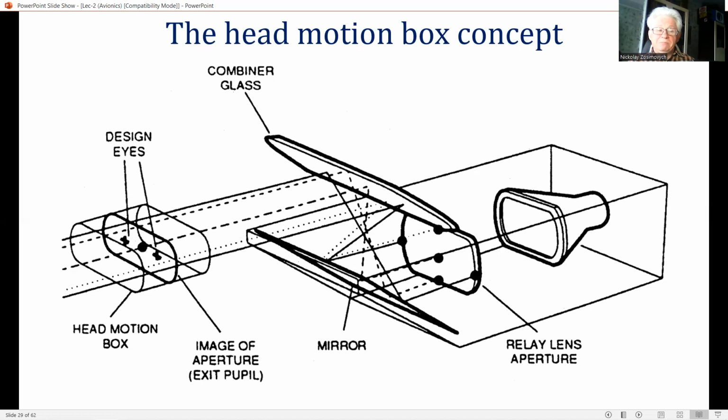This gives extremely good transmission of the outside world through the combiner. The outside world view through the combiner appears very slightly pink, as the green content of the outside world with a wavelength of around 540 nanometers is not transmitted through the combiner.